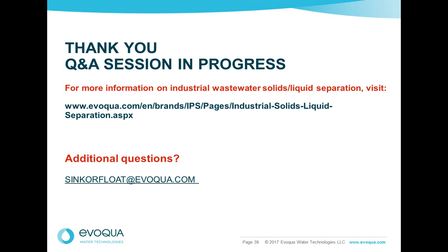Yeah, that's another real simple sounding question that's got some long answers, but we'll look at it from various points of view. Depending on the type of system, we'll tend to look at a holistic approach. We'll look at upstream processes to see how they're impacting the clarifier performance, whether it's variability in load or variability in hydraulic flow. And if it's a complex wastewater that's a composite of many streams, we look at whether segregating a single stream results in improved settling. So that's kind of the back end of it.